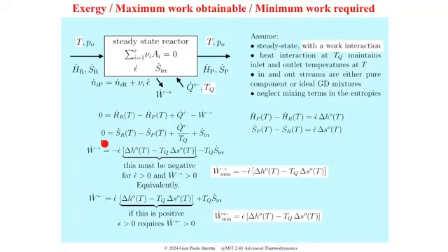So the work, in some cases, depending on the conditions and the values of these properties of reaction, sometimes you can do work, and the maximum work you can do is given by this. And if you have entropy produced by irreversibility, that will detract from the maximum you can do, so your actual work will be less than the maximum, because there is a minus sign here.